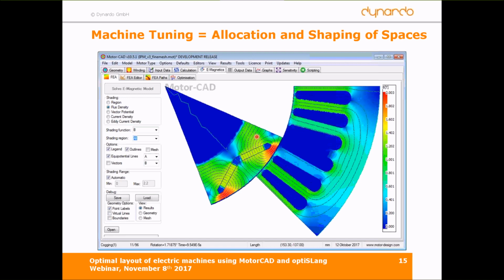And what's the physical background? Here we have the magnets. The magnets generate the magnetic field. Here we see the field distribution if the coils themselves do not create any field. So we can see just the field from the magnets, and you see field lines are shortcutting here, and field lines are going all around to close from, for example, the North Pole in front back to the South Pole in the back. And if field lines shortcut, they don't contribute to torque generation.